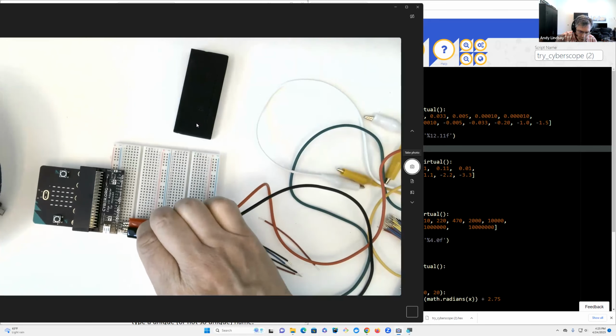You could jumper P2 up to a row above the adapter, stick the 3-pin header in up here, and clip onto it. That's doable. Or just let them be like that, because it's not really going to hurt anything if they touch. Aside from that, you'll get incorrect measurements.